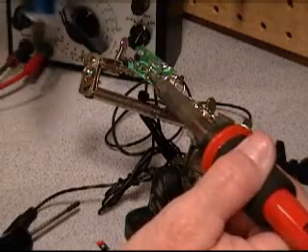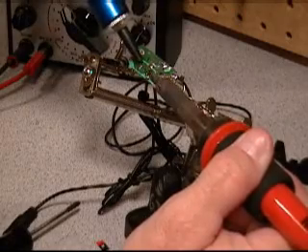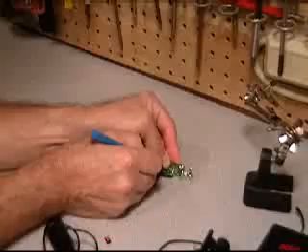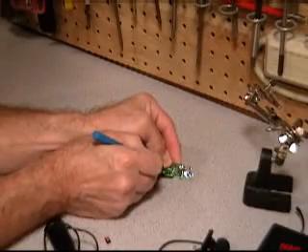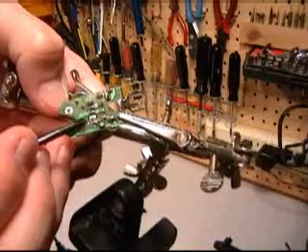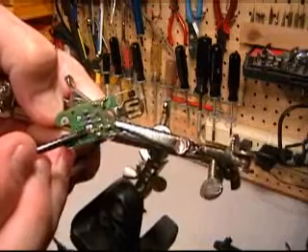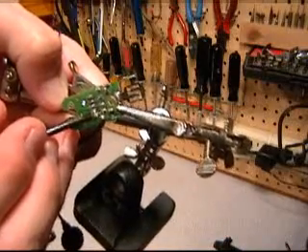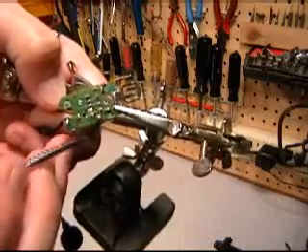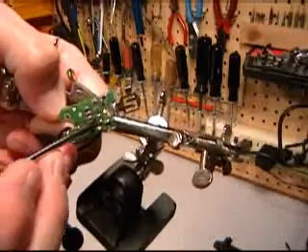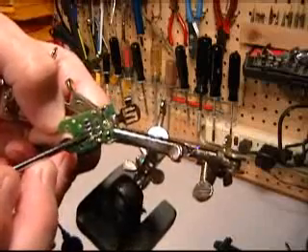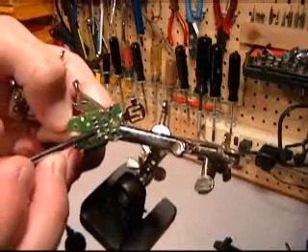First we'll remove a little bit of the solder to make the trace a little bit easier to cut. Now we'll cut the trace using an X-Acto knife. This is where I cut the switch trace, right between these two posts. Now we want to run a jumper from this side of the capacitor to this post of the switch.